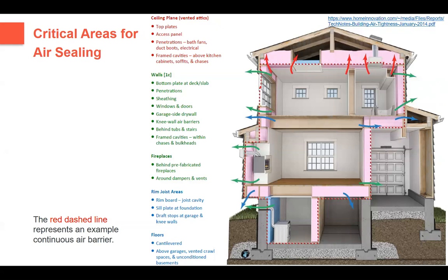Here we see a graphic of where our typical leakage points are, and you can see they're all over. We have cold air usually leaking in down low in our buildings, and then, as I mentioned, rising up and leaking out through attic hatches, upper story windows, or joints between the walls and the ceilings. Those are notoriously leaky places in commercial buildings. Might be soffits or recessed can lights or other utility penetrations if we have any utilities up in the attic, which is not uncommon. So a lot of different areas to pay attention to.